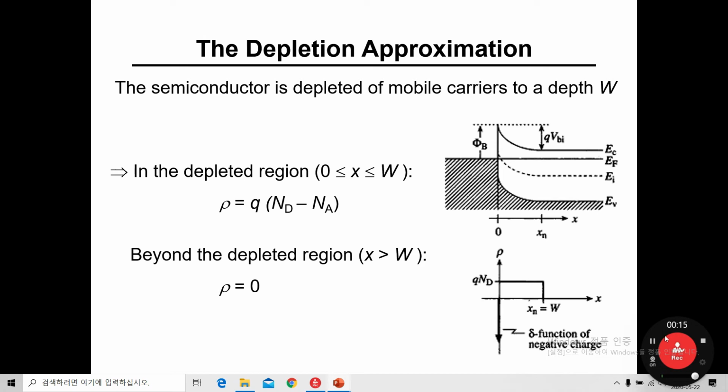So basically, on the right hand side, you can see the energy band diagram of MS contact at thermal equilibrium, since the Fermi energy level is single valued. In other words, the y-axis in the energy band diagram indicates the energy of electron, and the Fermi energy level is single valued. So we can guess that this energy band diagram has been drawn at thermal equilibrium.